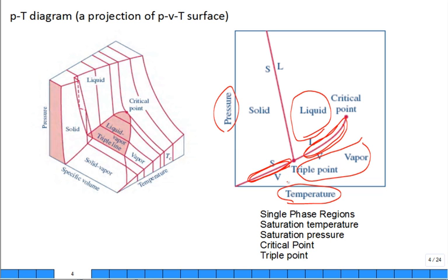a lot of times this plot will help you determine it, because you'll know something about the temperature and the pressure. So if I know the temperature and the pressure, and maybe I plot it and it goes like, oh, there it is, then I know I'm in the vapor region. Maybe I plot it and the pressure temperature shows up there. Well, then I know I'm in the liquid region. Or if it shows up precisely on the line, well, I'm in the 2-phase region.